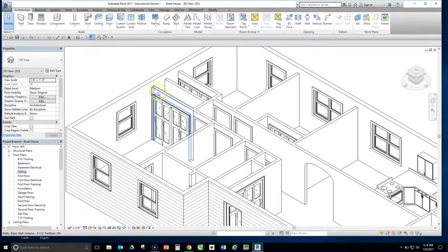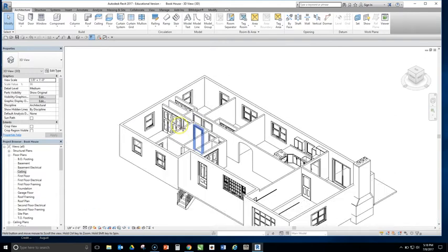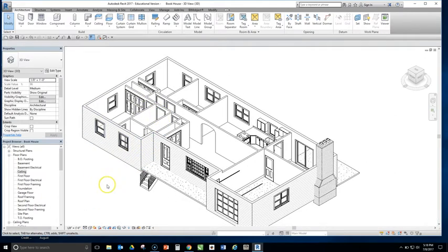Now the reason for that is this ceiling that we're going to create is actually made out of 2x10s with drywall on the bottom of it, and it actually sits right on top of these walls. And it will actually cut out the exterior wall out to the siding. So the siding will cover the edge of the ceiling, okay, but the wall inside there will be removed, which is why I say it represents the type of construction we're doing better.